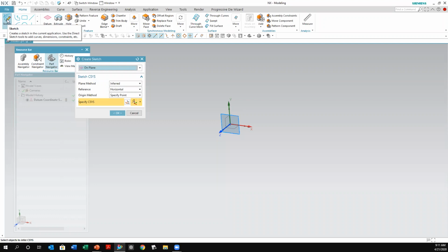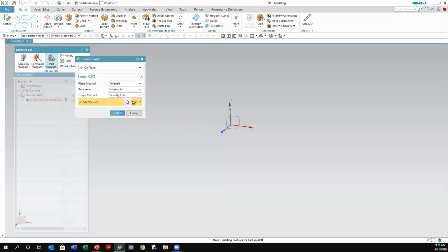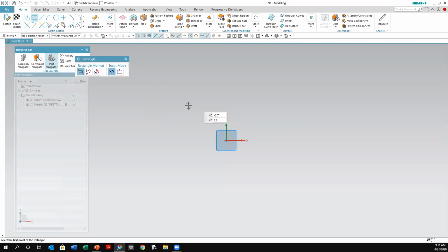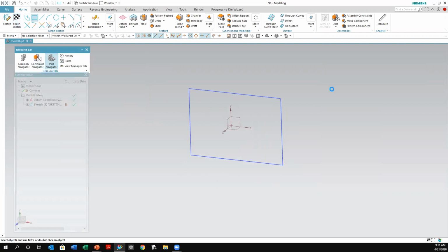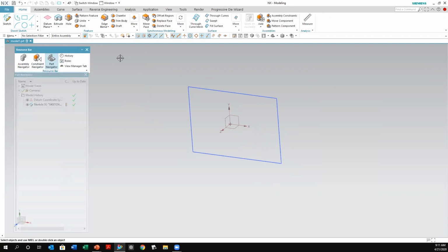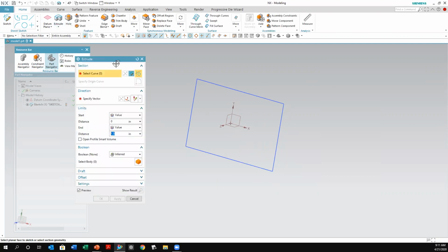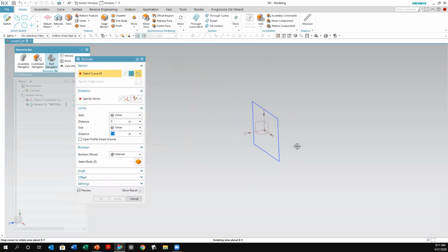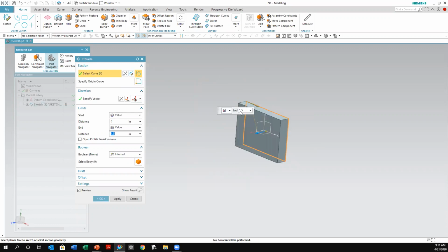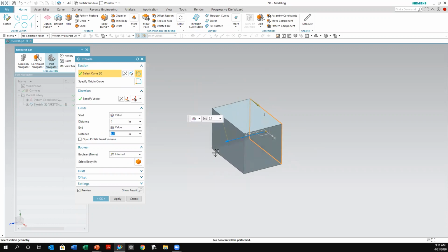All right, in this case, I'm just going to simply create a sketch here. Okay, so I'm going to say, define that already for me. That's fine. I'm going to select that one right there, and select that plane, and then go ahead and select my rectangle again. There it is. Right click to finish. So I'm done with that sketch. Then I could come back and click on the extrude command, and in here I could simply select the sketch that I just created. You see that? Now again, I could drag that whatever distance I want, or enter the value right here.